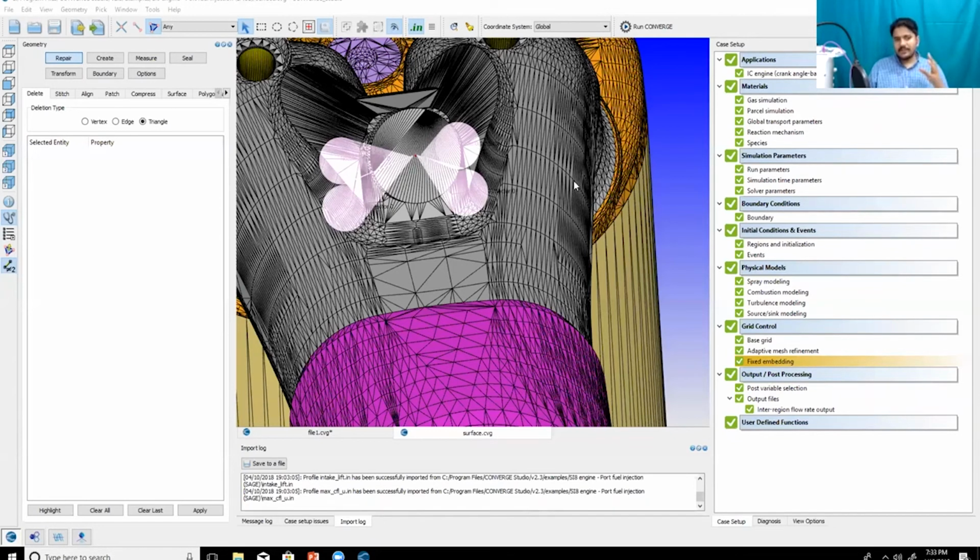So that is another thing. At the end of the day, with respect to all of these things, it's a system that depends on a lot of factors. So here you need to make sure that your mesh refinement is correct, but it should not be too refined. One of the things that people immediately think in CFD is that if I keep on refining, my results should be super accurate. The problem is that's not true, especially if you're using a turbulence model.